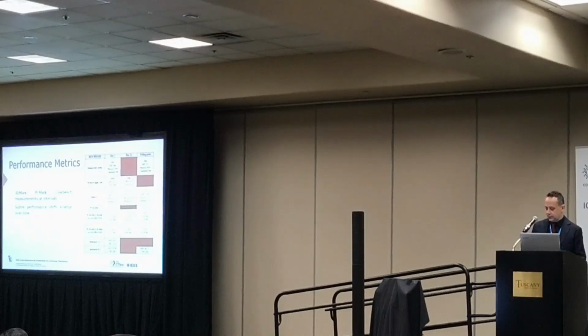We confirmed that the failing was related to the CPU by replacing it with a brand new one, on which we performed the reballing process, because the soldering ports are a very common reason why these components also fail. After we installed the new CPU, the computer was operating normally, so we could confirm that this problem was related to the CPU.